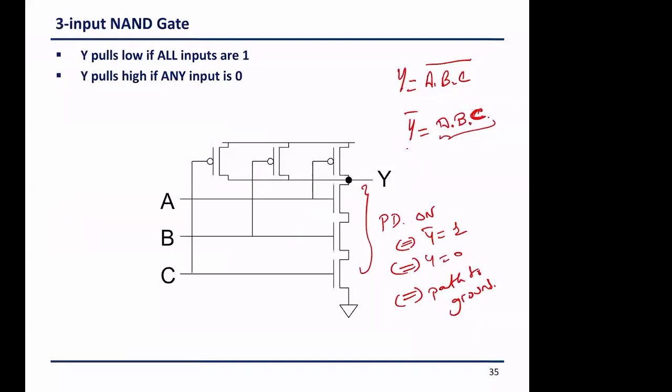Okay, and as we have seen in the behavior of the pure switches, if they are NMOSes, so the pull down, I always build it from NMOS, and they are active high, so I can have correlation. So the AND is really A in series with B in series with C. So I put A in series with B in series with C.